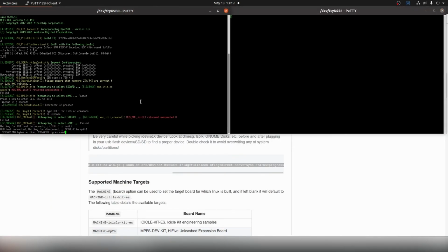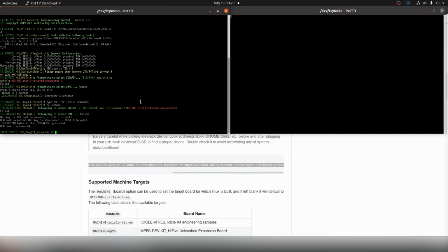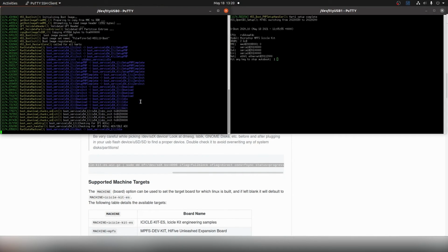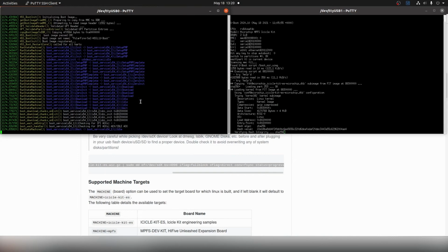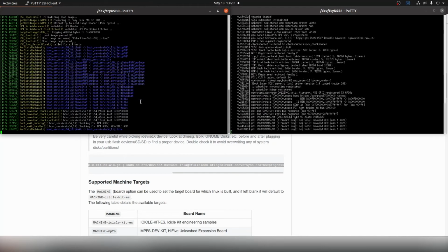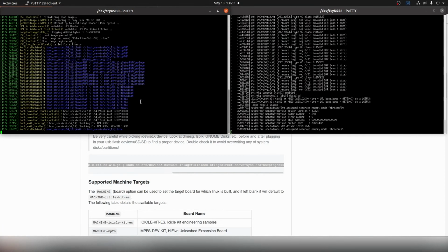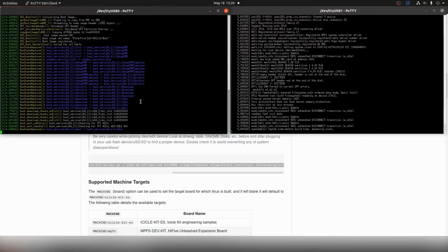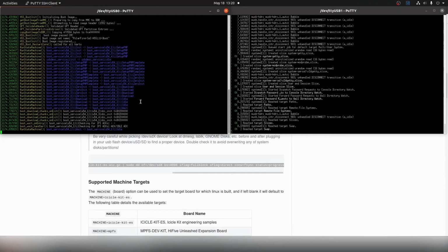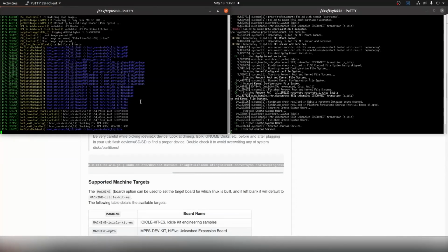Now, if we return to the terminal for the HSS and enter Ctrl-C, we can unmount our drive, and then if we enter boot, we're going to start up the Linux image. If you get some MUSB errors, like the ones shown here, you can disconnect the micro USB cable connected to J16 to get the errors to stop.